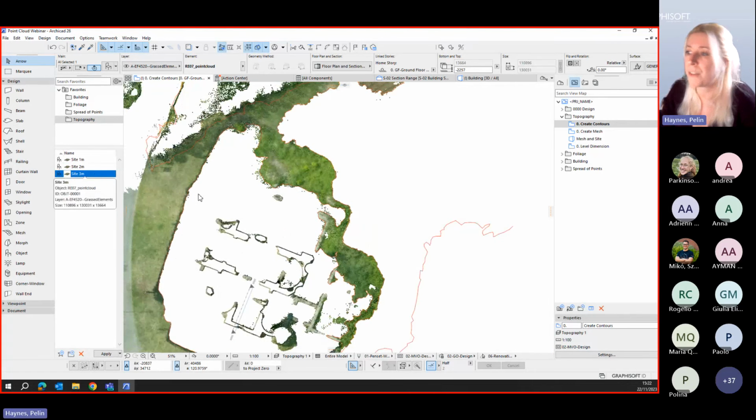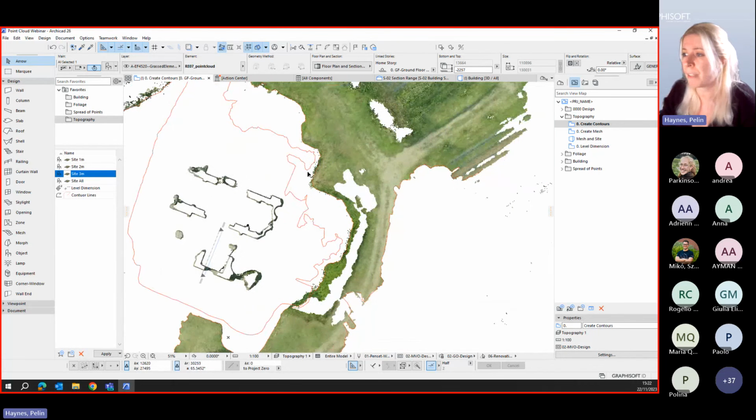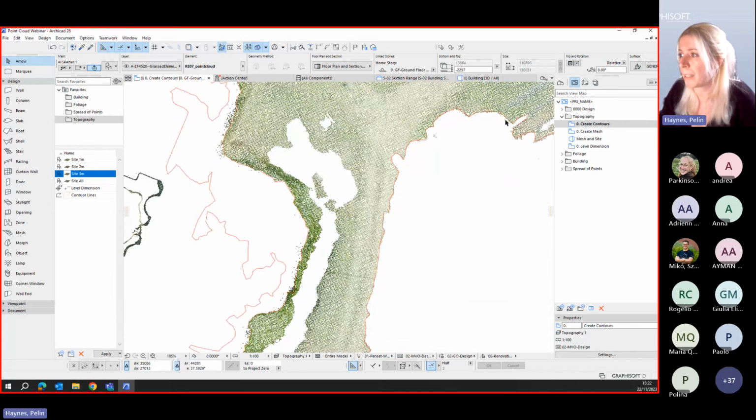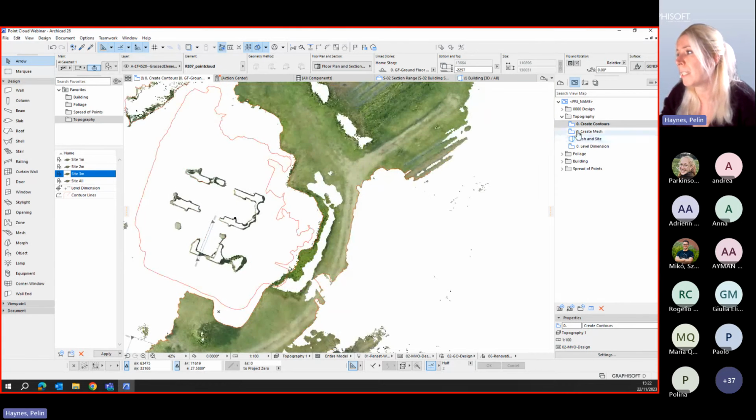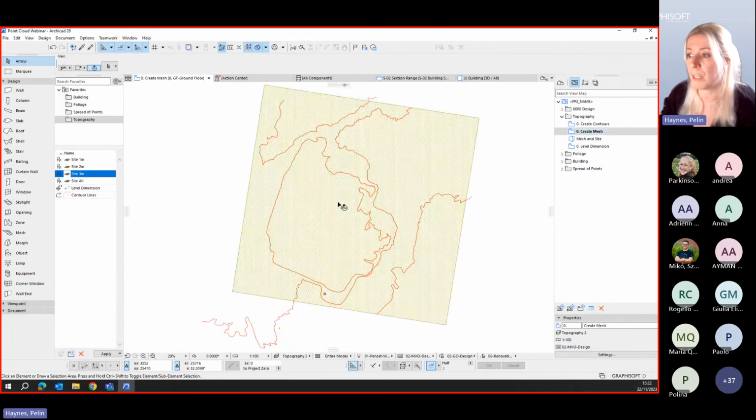Again, if I go to the 3rd meter, I will see a different part of the point cloud. And again, just following with my spline tool, polyline tool, whatever tool you like, I'm just following these. It's literally several clicks that you can follow. And once your contour lines are all predefined, you can start creating your mesh.